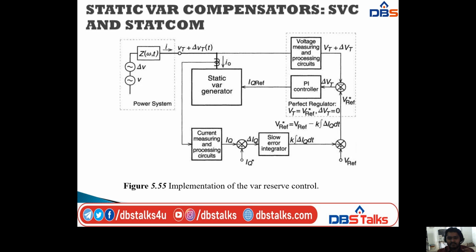Then it is given to the feedback, which consists of the reactive current IQ, and after this it is converted into delta IQ, the change in the reactive current. This is given to the slow error integrator, and then to one more feedback. It consists of the V reference value, which is given to the effective value of the reference, that is V reference star, and it is given to the PI controller. The output of this is the reactive current reference value, which is given to the static generator. Like that we are taking this one.